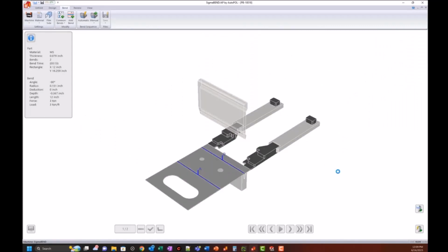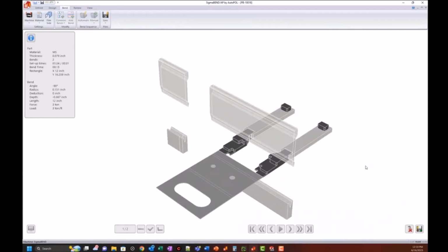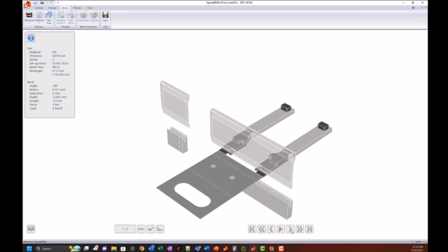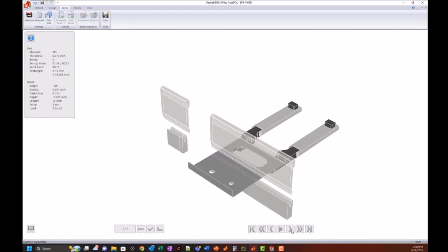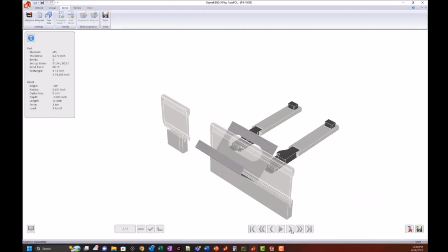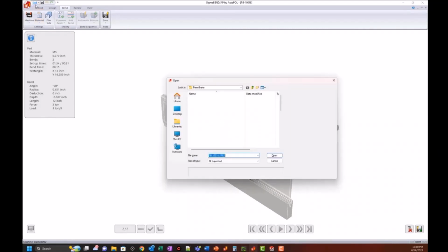And when I get to the step in the process where I'm setting the tool station, I have a new button here, so I can open this and see previously saved station setups. So I'm going to tell the software to select this previous setup and see if this part can fit on the stations already. So it's gone through, analyzed the bends that were already on the part and the station I've told it to use, and just making sure that everything can work. Everything looks good. I now, without changing any tooling, can perform both of these parts using the one setup.